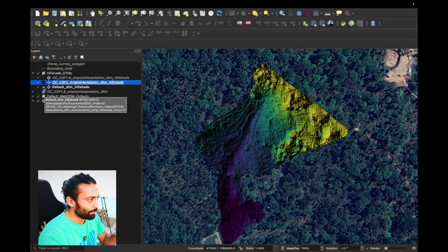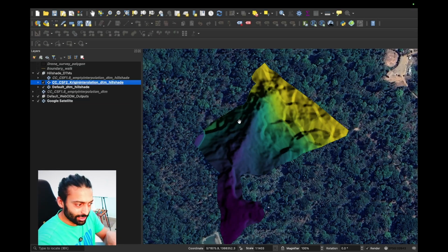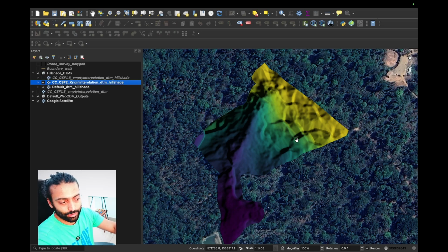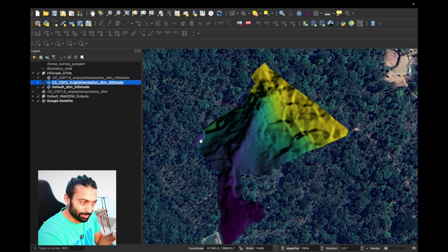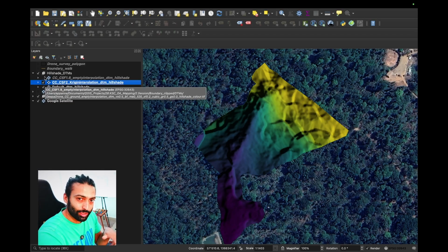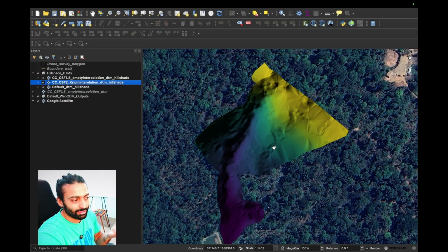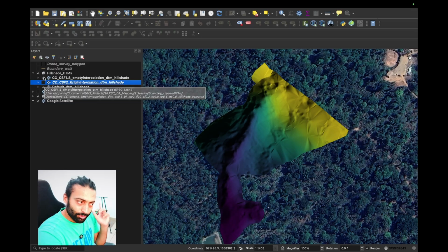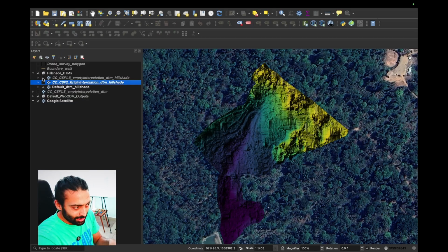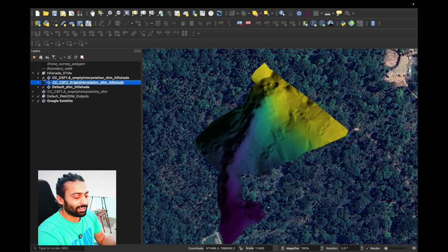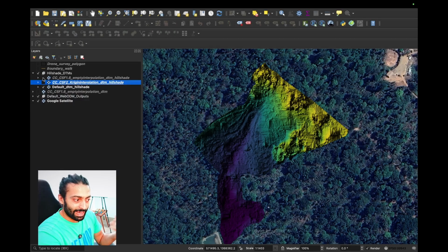So this is how this looks. This is the default WebODM hill shade. Then we did the Kriging. As you can see, there are plates stacked. In the Kriging algorithm, there were the plates stacked, and also this little bit of lost information, which actually prompted that cleanup process. And then finally, after the cleanup, by setting the CSF to be 1.8 and an empty interpolation, we have the ideal DTM. Now, if I compare it with the default DTM from WebODM, we can see that there's quite a bit of difference. This looks like a very usable and actual surface of land, and this is what we're going to go with.